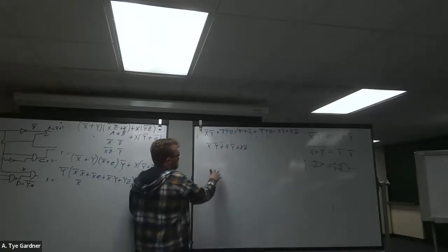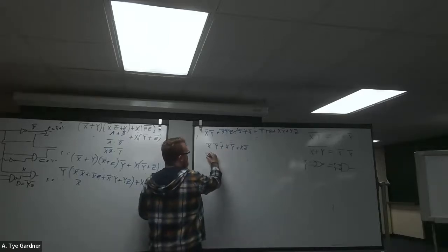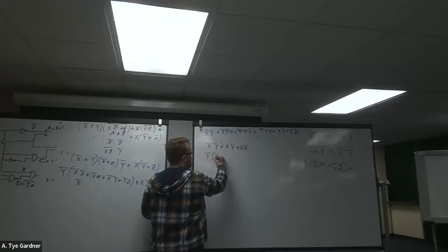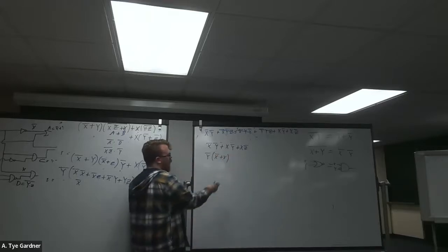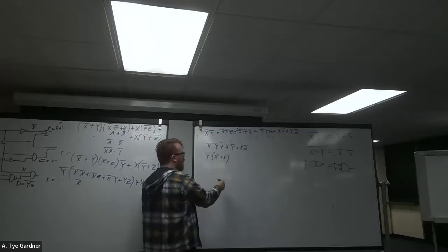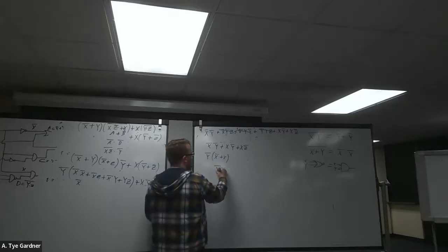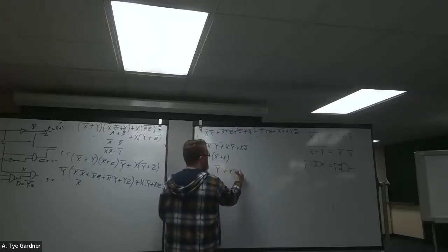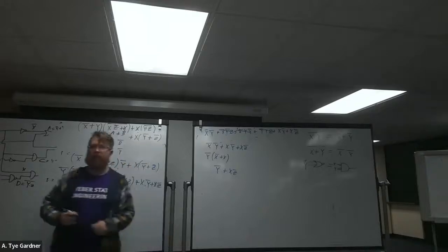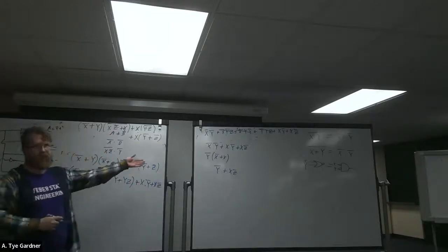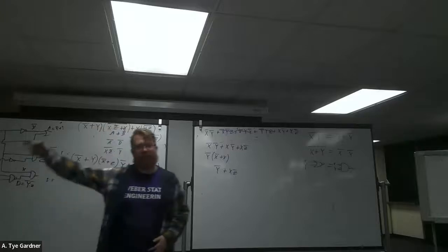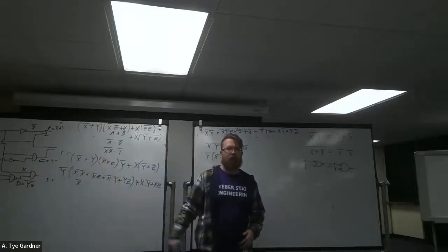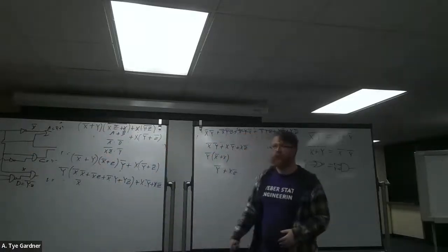So we have this not Y that I can factor out, which is not X or X, which is just exactly one. So I have not Y or X, not Z. And that's my final circuit. A lot more simple compared to the giant mess that I had erased before. Well, half erased anyways, right?